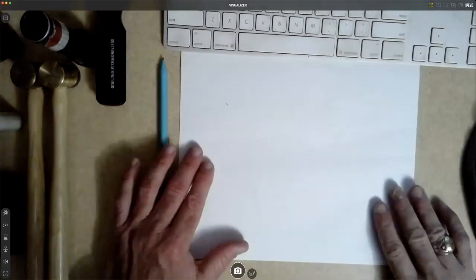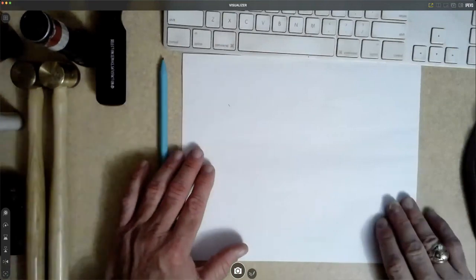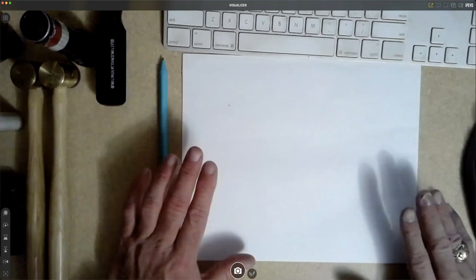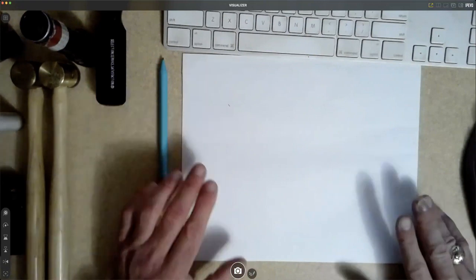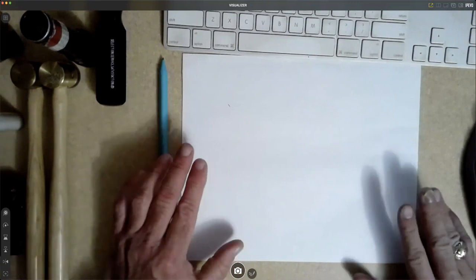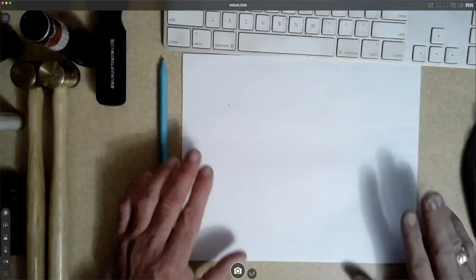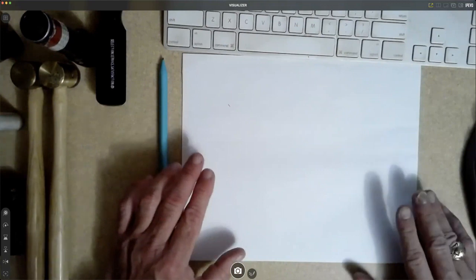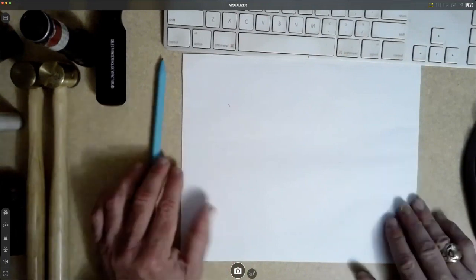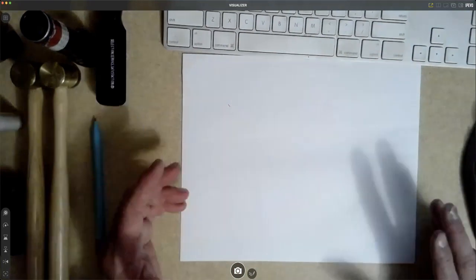With ARs, it's a little bit less of a concern. But if you're doing anything with a bolt action, doesn't matter who the manufacturer is, when you're doing your headspacing, you have to have the go, no-go, and field gauge to make sure that you're getting it seated to exactly the right depth. They're not very expensive. I think a set is $15 to $20.